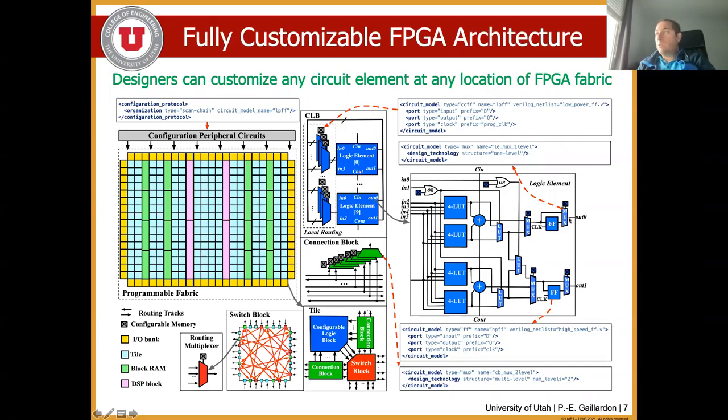Well, how do you do that? We want to say that your block right here is actually using a multiplexer, and this multiplexer is to be a one-level structure or a MUX tree or a two-level structure or whatever that is that you fancy for your FPGA architecture, right? But you're able to describe that at a very low level. Similarly, so that's created auto-generated block. Similarly, you could say that this flip-flop is actually going to be implemented from this Verilog file.